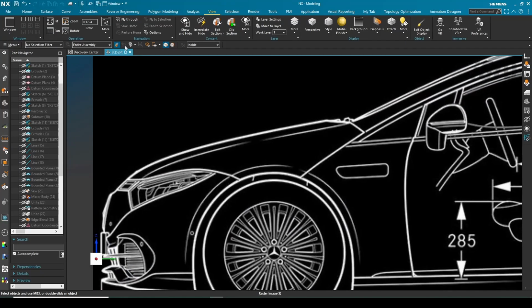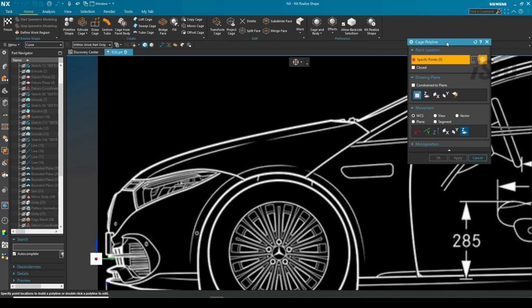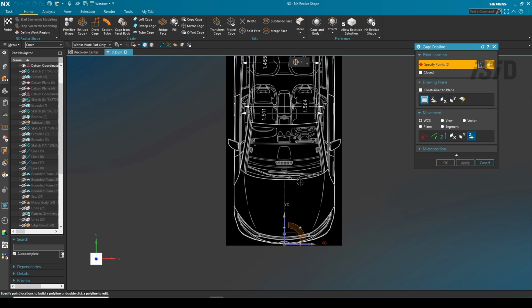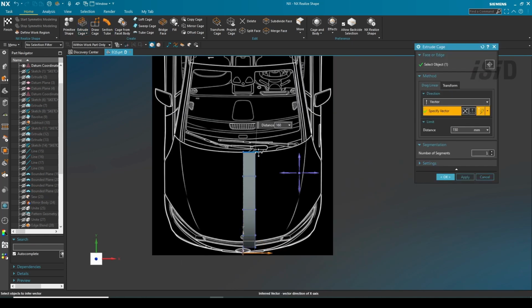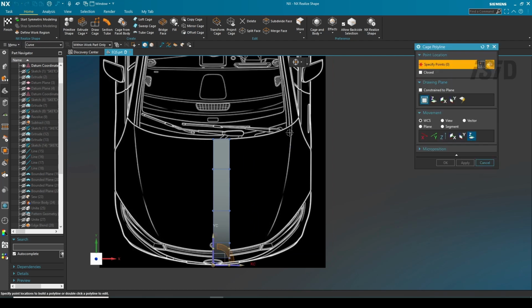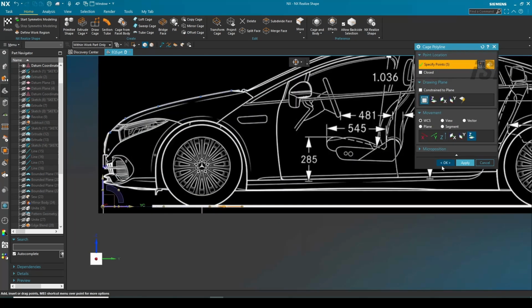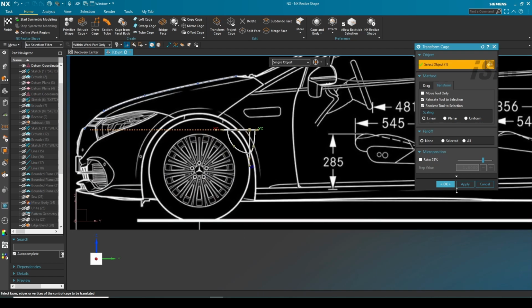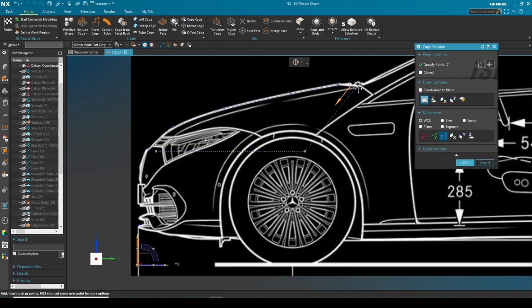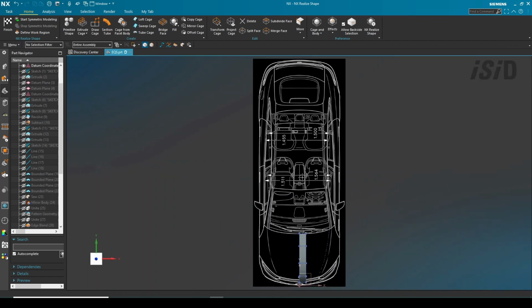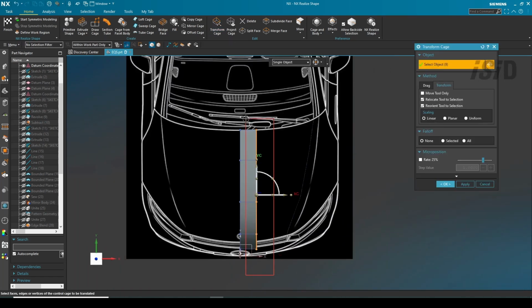To begin with, I always start by creating the surface in the hood area, using a cage polyline, and then you can see I extrude it a little bit horizontally. I have prepared another cage polyline near the hood area and adjusted some cage vertices a little bit following my image, and then I connect them together using the loft gauge.